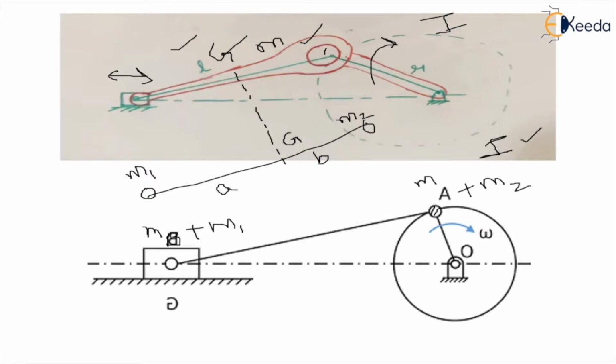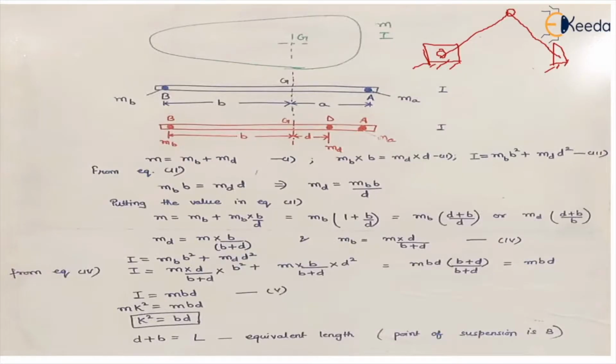We have already discussed that it is not essential that the point masses be positioned at the ends of the link, but in case of the connecting rod, initially we are adding these masses at the ends. So part of the mass gets added to the crank and a part of it gets added to the piston. So by converting a connecting rod into a dynamically equivalent system, we are adding masses at the crank pin and the gudgeon pin.